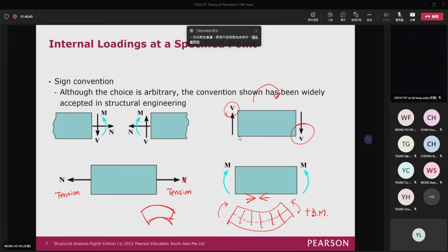If a bending moment acts in the negative direction, that means it is concave upward, then it bends like this, which makes your structure unhappy, and we call it a negative bending moment. I think it is easier for you to memorize the sense of positive and negative for bending moment. Okay, so you may ask, hey Simon, for the equilibrium equation, you always assume that pointing upwards is